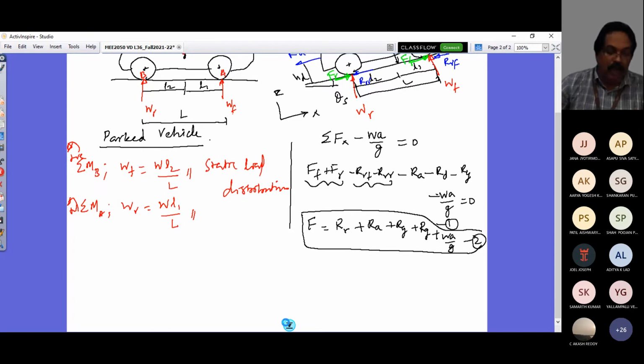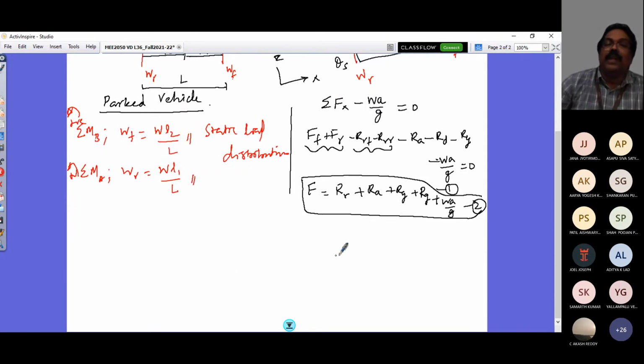Here, the forces developed at the tire road interaction are what make the vehicle go forward. So the net force would be this force minus these rolling resistances. I'll take the rolling resistance to the other side and keep all the remaining on this side.